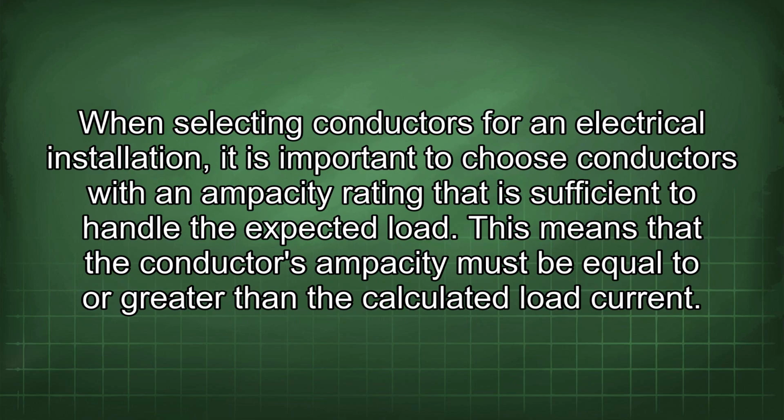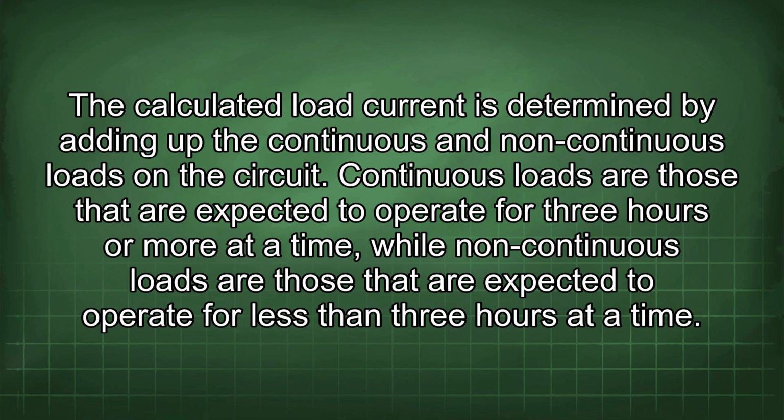When selecting conductors for an electrical installation, it is important to choose conductors with an ampacity rating that is sufficient to handle the expected load. This means that the conductor's ampacity must be equal to or greater than the calculated load current. The calculated load current is determined by adding up the continuous and non-continuous loads on the circuit.